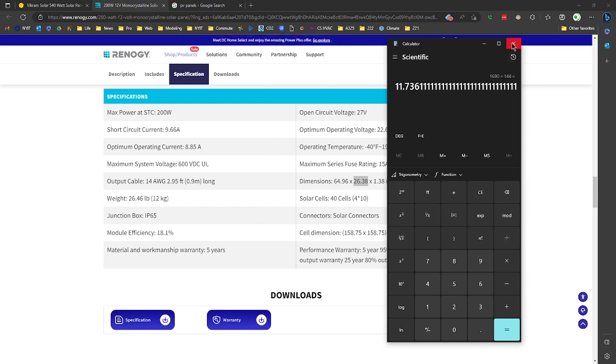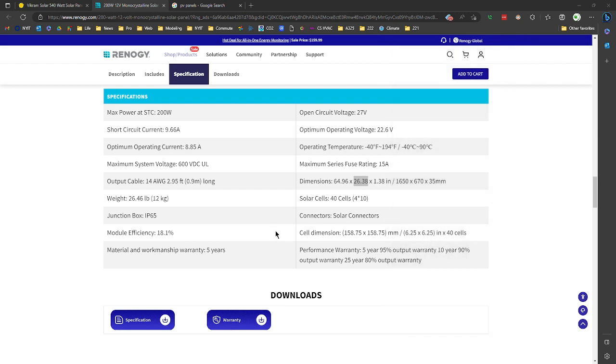And if it's 200 watts divided by 12 square feet, it's a little lower, 17. But we're in the ballpark. The other one was 19 something, and this is 16 something. So that other panel seems like it was a little more efficient. But anyway, 20 and 17 is what we're looking at.